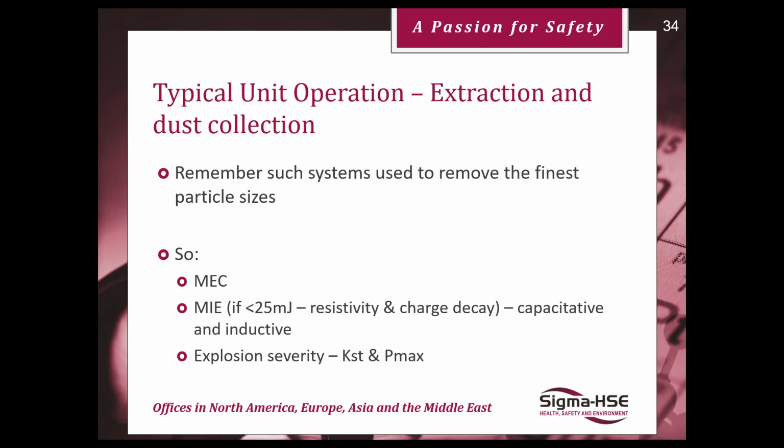And of course, in a dust collector, when you clear the filters of dust, you will be creating a flammable dust cloud, which if it ignites will result in an explosion because it's a contained system. You will have some means of mitigating the effects of that, typically a vent, and that's where you'll need KST and Pmax data to be able to design that vent, suppression system or containment system appropriately.